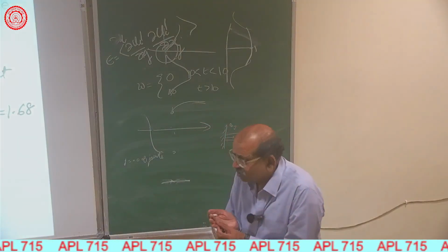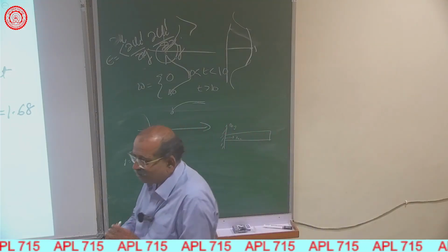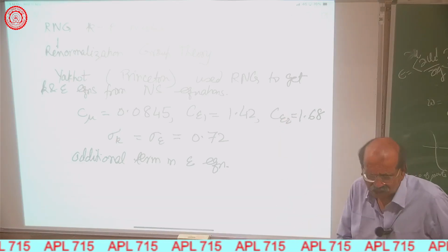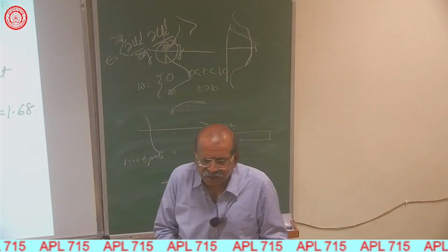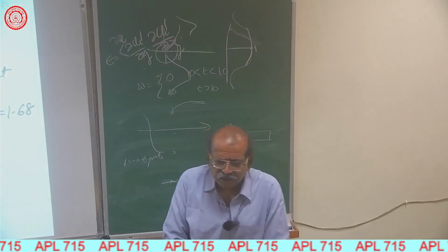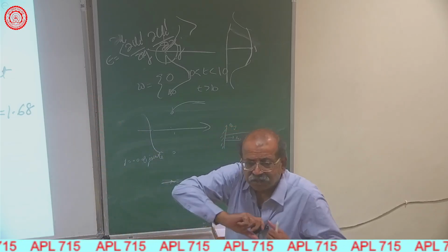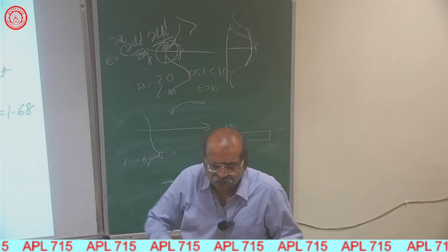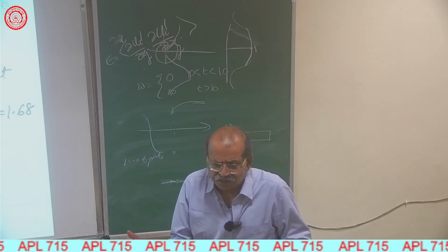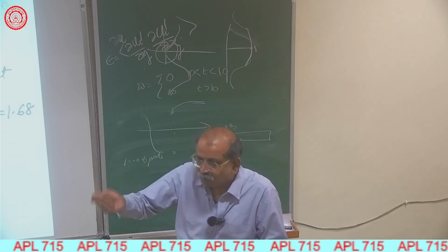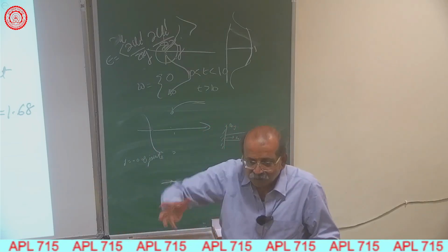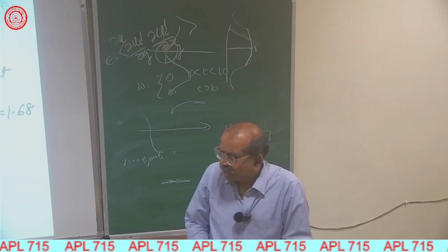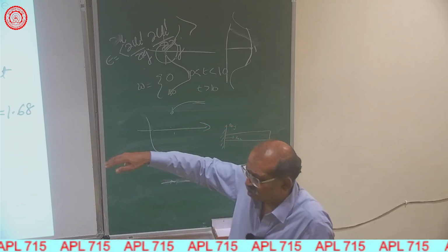Now in tomorrow's class, we'll still have tomorrow's class, it's not that we'll not have it. Even in these, the values are not way off from the experimental values which Launder and Sharma got. And then people keep on changing. Sometimes you have a flow with curvature, then you will use some other values. You will put a curvature term also in the equation. So sometimes you even modify the K and epsilon equations, put some extra terms there like with curvature and all. That is done. And I'll talk of some more variations of these models tomorrow.